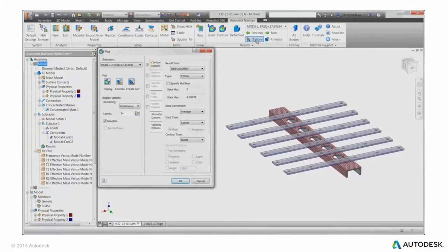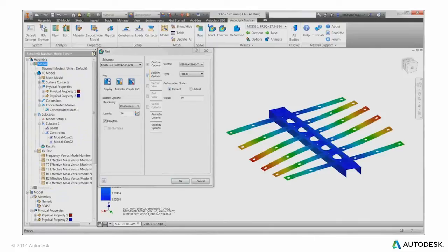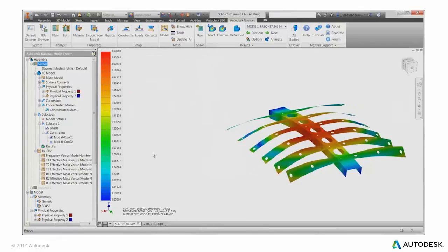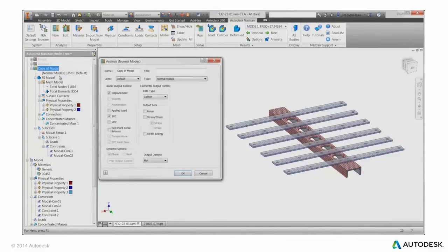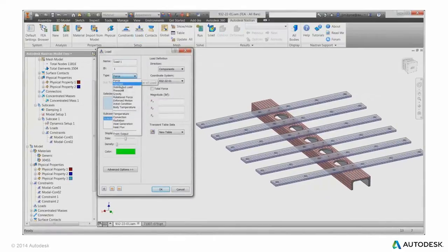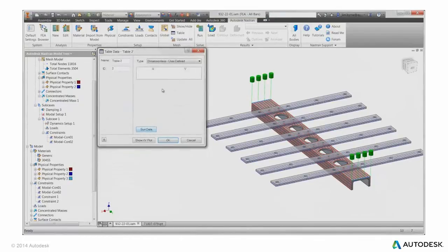So we can run vibration analysis to see how it's vibrating. And obviously as we made the arms longer, the design is going to be more flexible. So what we can do is simulate how the machine operates. We can apply a velocity to the end of the C channel to represent its upward movement, and we can also define that it comes to a stop after a certain time. So we can define these load steps.